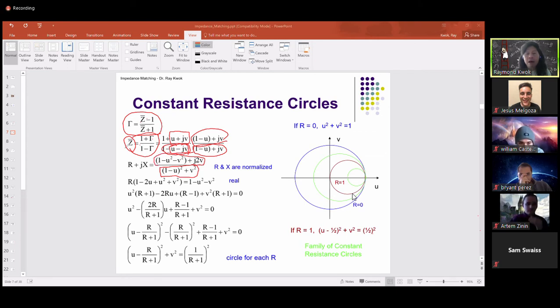That's my z bar. What is z bar? Again, the real part is resistance, the imaginary part is reactance. This is supposed to have a bar; I'm just getting tired of writing a bar. So this is supposed to be R bar plus jX bar. I'm just going to skip all the bars. Anything I write from this point on is normalized. So R is really R bar, the normalized resistance.